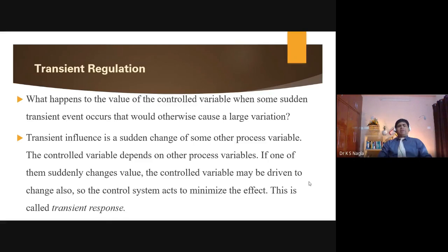You suddenly change the temperature from 70 to 90 degrees. The moment you change it, there is a large fluctuation, because you are switching on the heater, you are opening the steam valve, and the internal temperature has its own dynamic properties at that time, so there are sudden fluctuations.